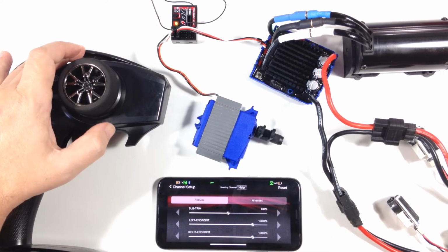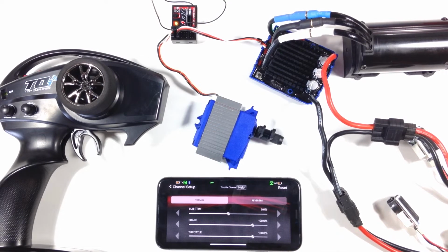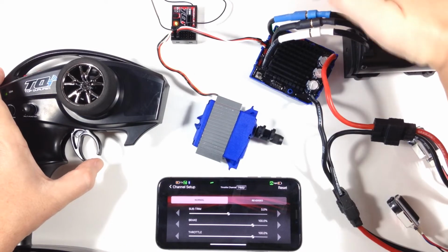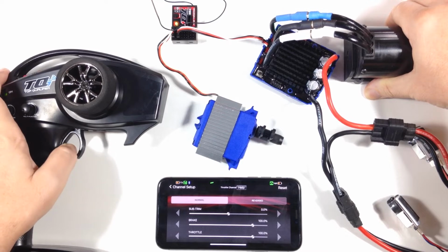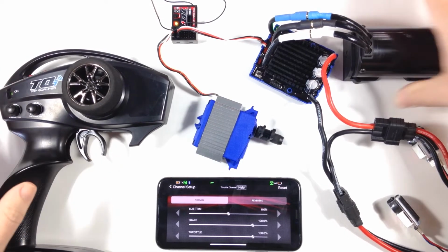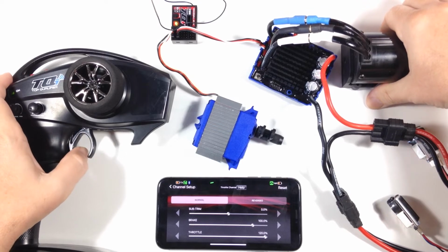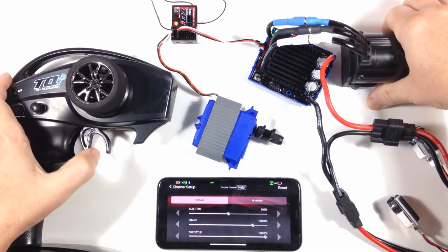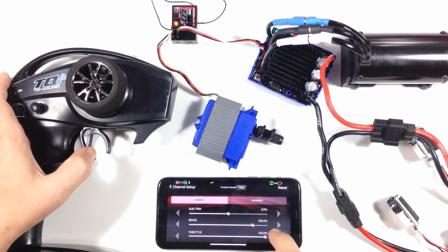So I'll reset that and we can see on throttle, so this is calibrated, it's running 4S so I can hit full throttle. If you look at the green light you'll see it hit full throttle on 100%. Now if we set 120% throttle, you can see it hits full throttle there and there's deadband, as you'd expect from an increased range and remapping that to the trigger input.